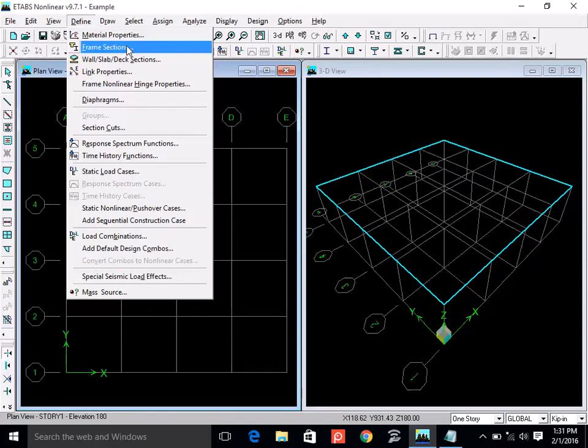Now about the width, this is depth, about the width. Generally there is a practice among engineers, there may be some exceptions, but generally we start from 12 inches and then round it off to the next 3 inches: 12 inches, 15 inches, 18 inches. But 12 or 15 inches is a very reasonable number in real life practice.